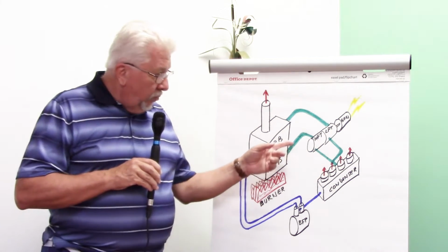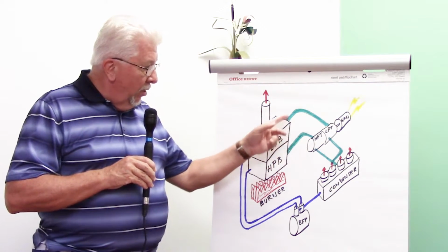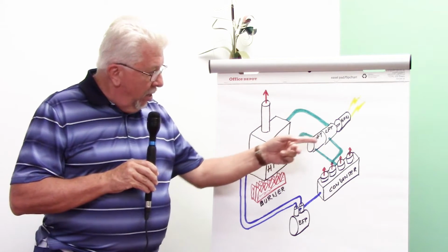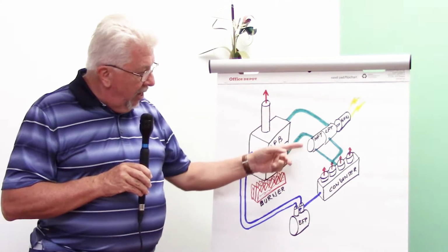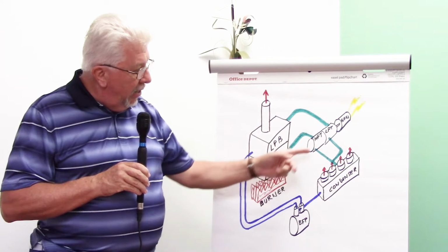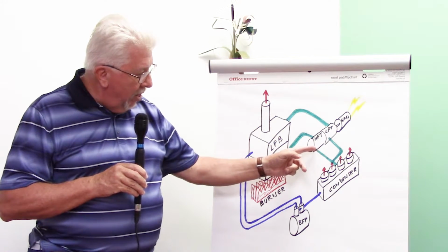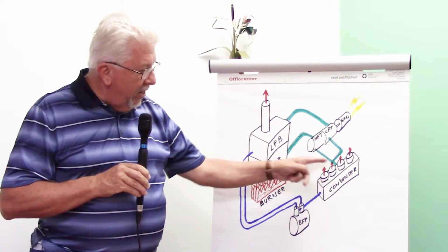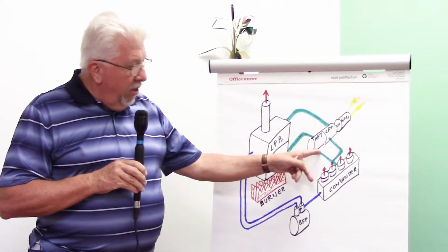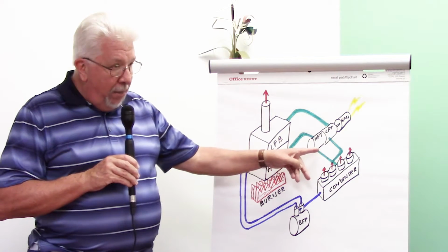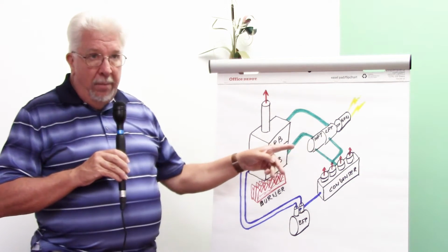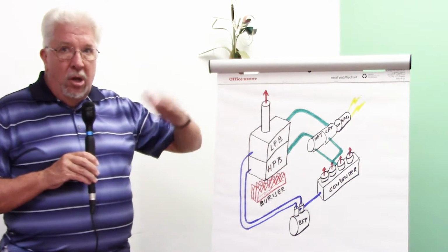Now, the high pressure steam and the low pressure steam both act on the turbine blades and generate electricity, and then they get exhausted. Okay, the turbine exhaust from the low pressure side is combined with the turbine exhaust from the high pressure side, and it goes to a condenser. Now, these are operating at a whole different situation. They're operating at a slight vacuum. They're running about 5 psi below atmospheric.